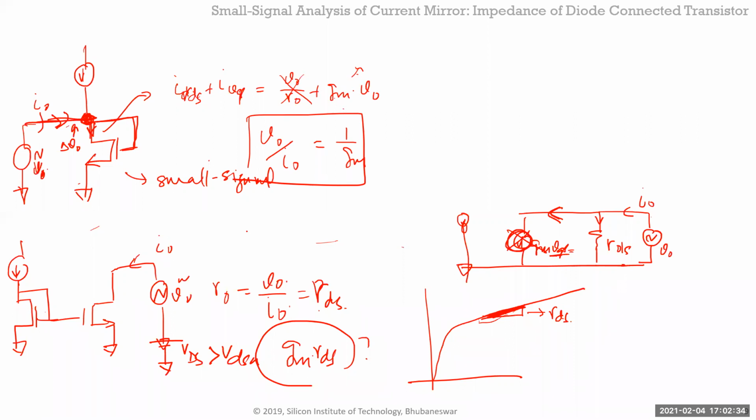So that's a small impedance now instead of a large impedance. And that's what you want, right? This is like a TIA: you're taking a current and generating a voltage. Whatever is generating that current, you want a smaller impedance so that you're not changing that current too much. So it's kind of an ideal TIA terminator. So draw the small signal and see if you get an answer which is 1 over GM, at least when you make all your R outs and everything infinite.